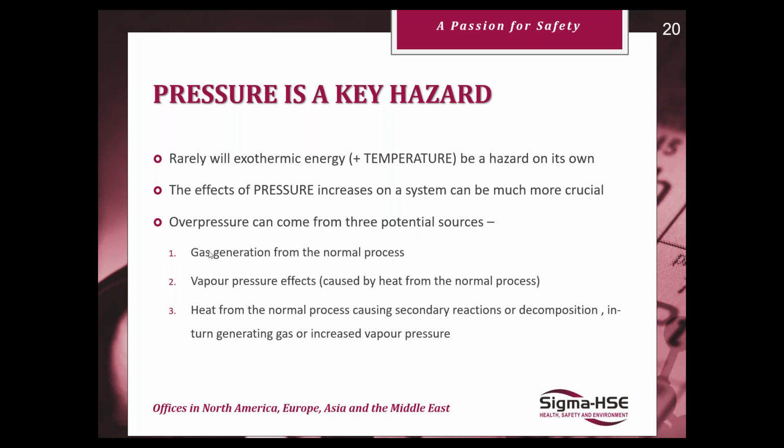Like I say, gas generation from your normal process. Is it producing a byproduct of a gas? Vapor pressure, you're heating your system up. How much vapor is going to be produced from some evaporation of your solvent? And then finally, just to wrap it all together, if you trigger a decomposition or a secondary reaction, this effect of generating gas or vapor pressure is only going to be increased over and over again.